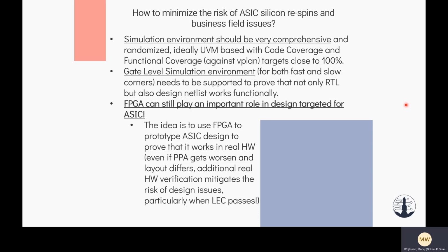So it is good to build a team of experts doing this verification, being able to exercise your design very comprehensively. Also, one more important testing environment is gate level simulation. This means simulation not with your HDL description of the design, but with discrete gates inferred from your HDL description. To get these gates, you need some ASIC implementation tool and a technology library on which you want to synthesize your design.